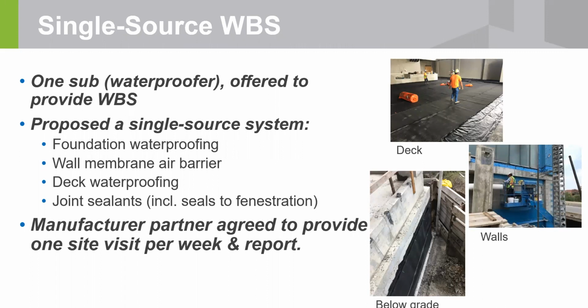So for meeting that air leakage, you're talking about a lot of different things that are affecting it, not just the air barrier materials such as what my employer sells, but anything that is joining to it or penetrating it. Specifically, you've got fenestration, cladding attachment, junction to other wall assemblies, junction to the roof. So someone has to really own this and bring it together.